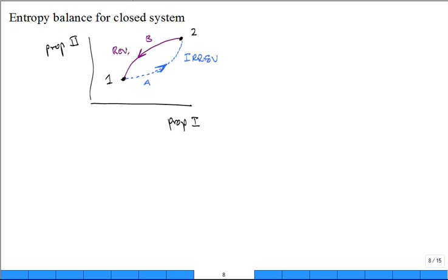Now, we can apply somebody's inequality. Carnot's inequality, Kelvin's inequality, Clausius's inequality. I forgot what Clausius's inequality said. Did it say the integral around a cycle of del Q over T has to be less than or equal to 0, and we turned it into an equality? We always say Clausius's inequality, then we write it as an equality, with a minus sigma of the cycle. Did you notice that? How many people like that?